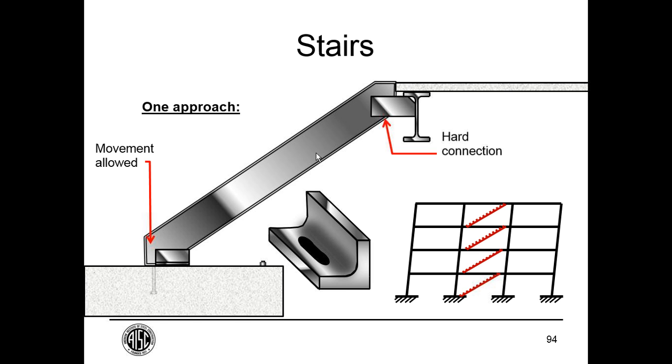At one extreme, you have a very rigid system, say a concrete shear wall, or even a steel plate shear wall is fairly stiff. You could have relatively small displacement demands for that stair, and so you may not have to worry about the relative movement of one floor versus another. But if you have a relatively flexible system like a moment frame, then yes, you do need to be able to accommodate those displacements. And I think this is not something new to the industry.